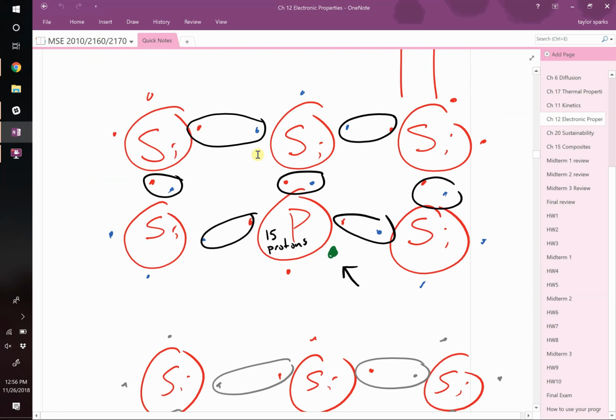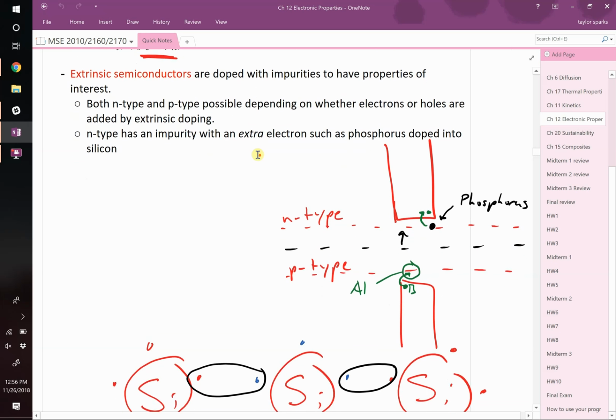Last time we said that you can have silicon, and if it's just pure silicon, then each silicon's got 4 electrons. It bonds with 4 other silicons. All of a sudden, all the silicons have 8 electrons, which is really just a way of saying that their valence band is completely filled, right? The electrons fill right to the top of this valence band, and so there's no empty seats here, and there's a band gap before you get to those upper ones, and so it's not particularly conductive. Intrinsic silicon is not a good conductor of electricity, right? You have to heat it way up. You have to give it lots of thermal energy before they start jumping that gap and conducting.